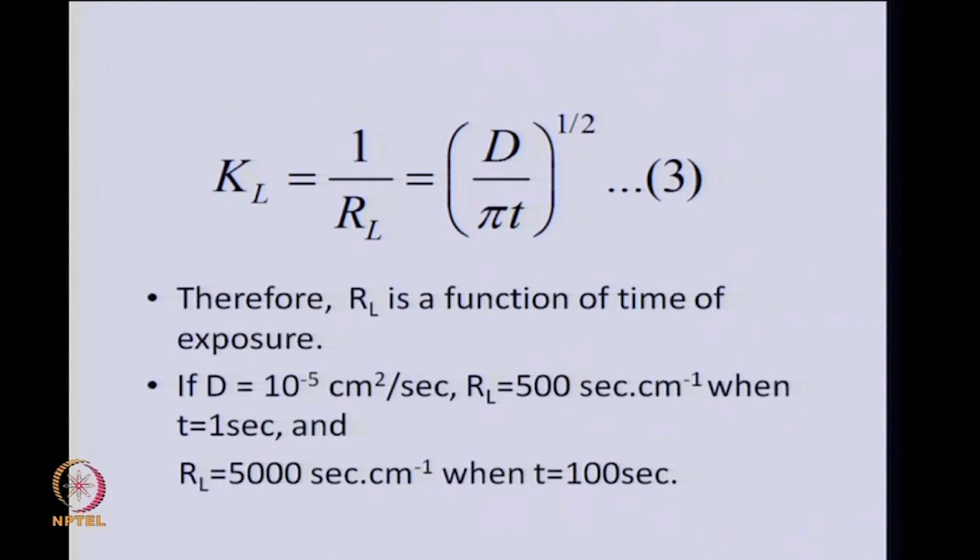Yeah. In this case, K is proportional to D to the power 0.5. Right. So, can we say we have applied penetration theory? Exactly. Yeah. This is basically, one may say, penetration theory, provided this time can be regarded as constant, but the safer statement will be that K L proportional to square root of D means that we have used some kind of surface renewal theory.